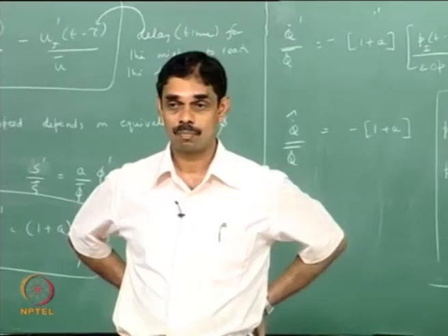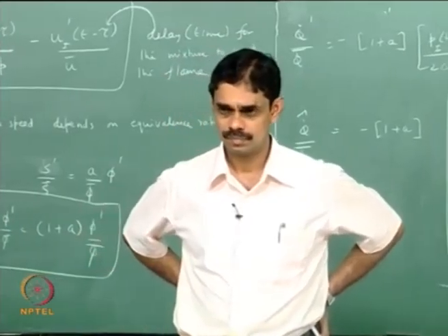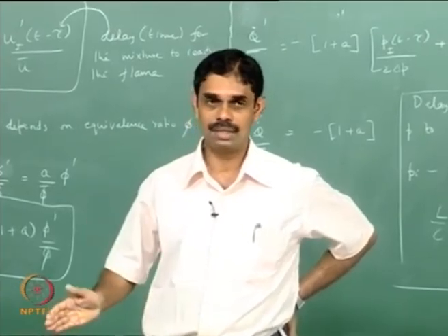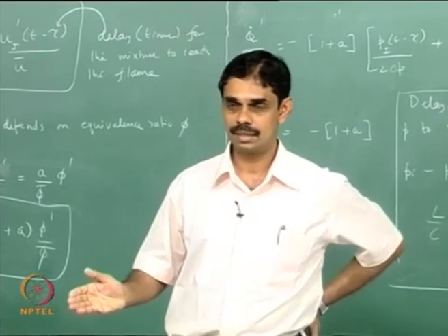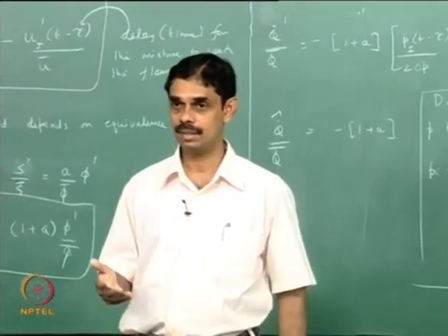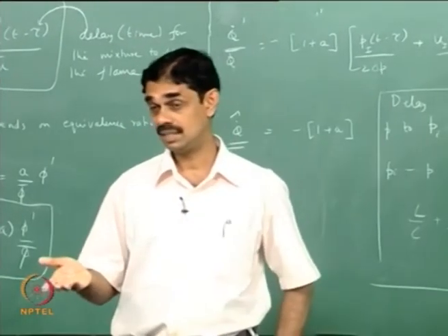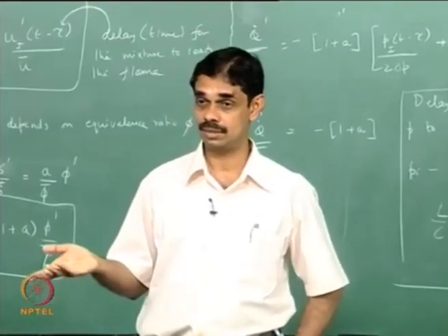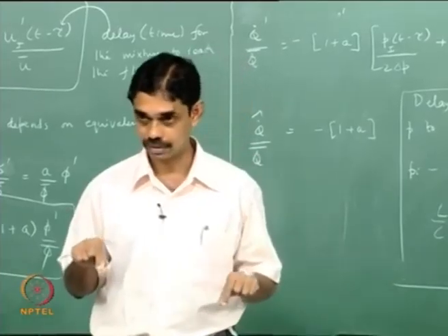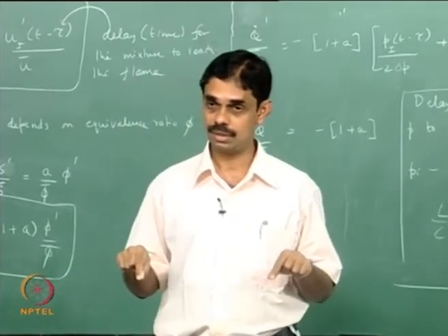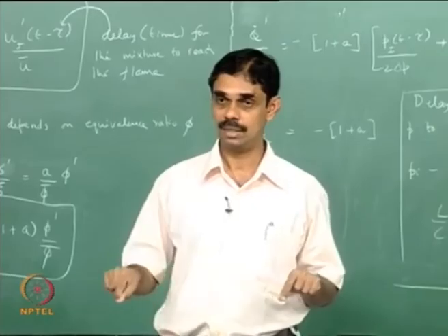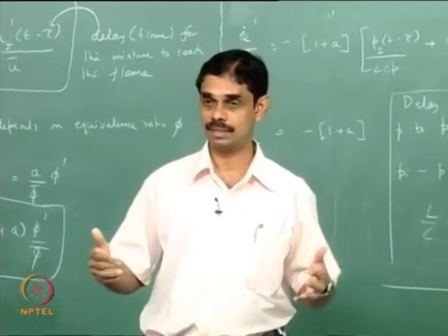Which is of the order of acoustic, like velocity of sound will be acoustic. I think what you have to do, if you are looking at it theoretically, is look at the eigenvalues of the linear operator, and if that is c, then you can call that fluctuations acoustics. If it is experimentally determined, you put pressure probes at two locations, cross correlate them and see what is the delay between them, and if that is the speed of sound, then you can say there is something acoustic to it.